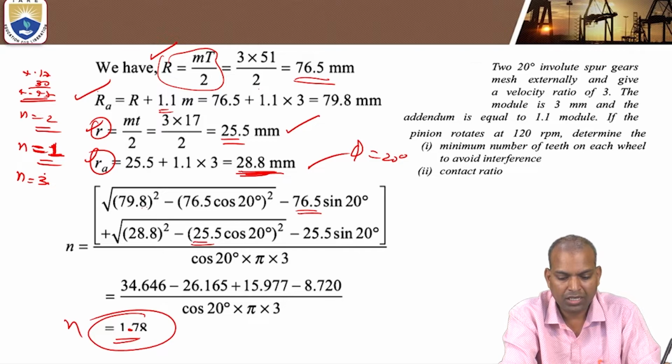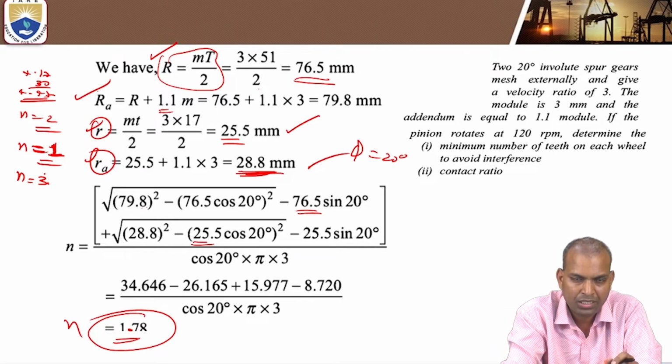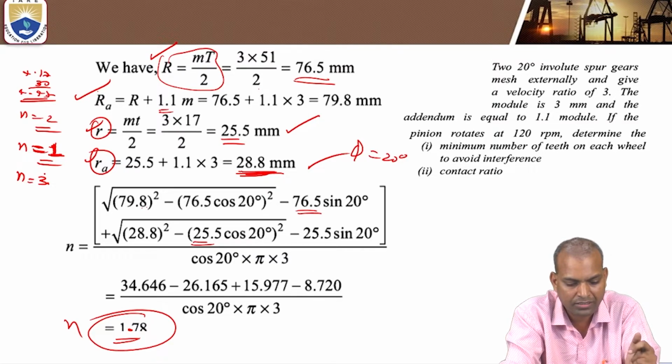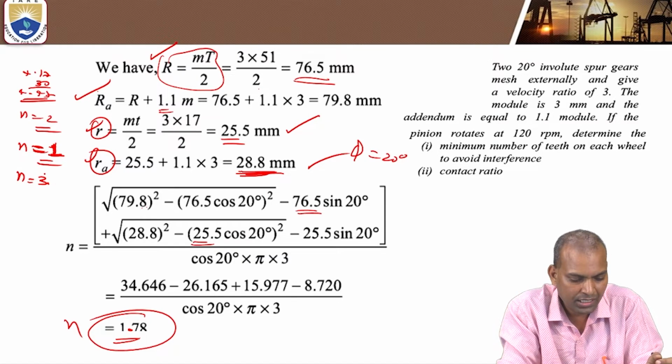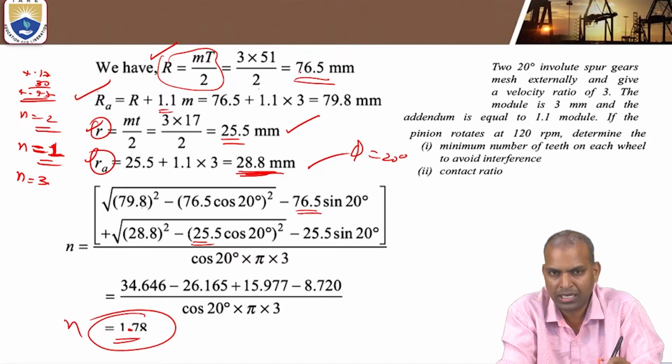It depends upon the geometry of the gear and pinion, the number of teeth in contact. Now, the contact ratio is dependent on the parameters of addendum circle and pitch circle radii of both pinion and gear, and also it is dependent on pressure angle.